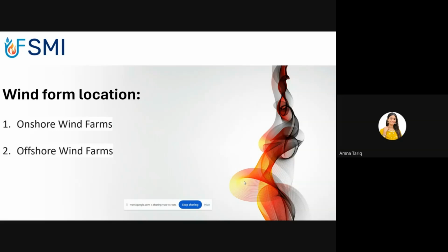The level of infrasound radiated by the largest wind turbines is very low in comparison to other sources in this frequency range, such as sonic booms, shock waves, and explosions. The danger of hearing damage from wind turbine low frequency emission is remote to non-existent. However, annoyance is often connected with the periodic nature of the emitted sound rather than the frequency of the acoustic energy.